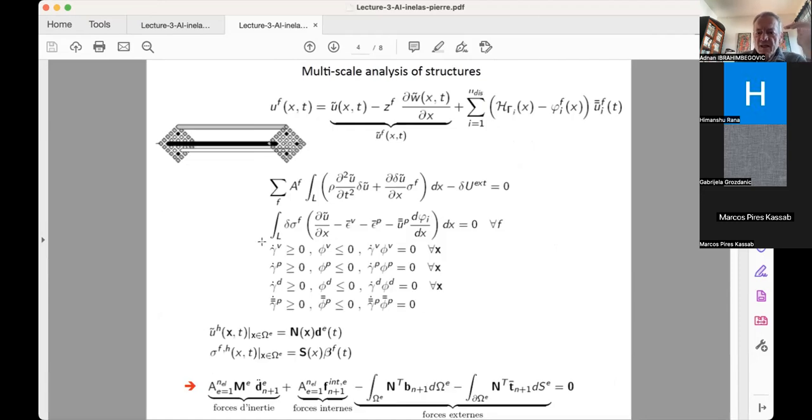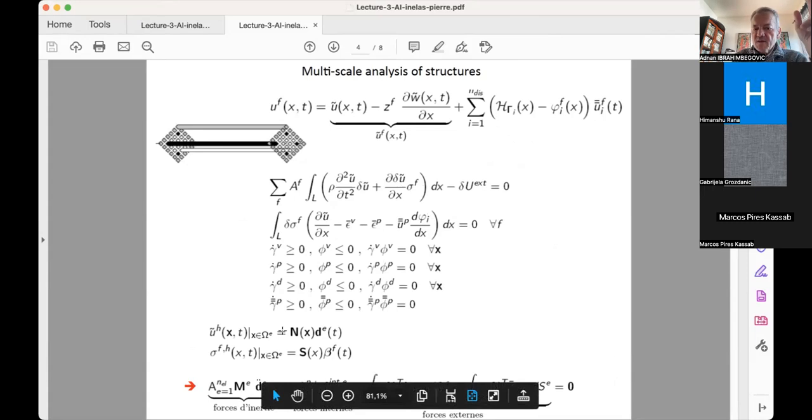In agreement with these criteria, every time there's a particular multiplier, either viscous, plastic, or damage, it has to be positive or zero, and the particular phi has to be negative or zero. So this is now something with the unknown displacements, other than the internal variables and stress. What we have done here is introduce direct interpolation of the displacement and direct interpolation of the stresses. It could be quite easy to do that.